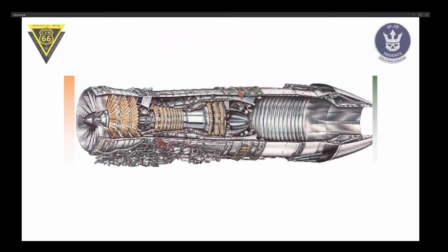Okay. Let's take a look at our engine. This is the GE F-110 afterburning turbofan engine. It has basically a couple of major components. The front one is our three-stage low-pressure compressor. It basically does two things. It creates a lot of thrust, because these fan blades blow air down the outer duct, which creates thrust, and they pre-compress air for the high-pressure compressor.